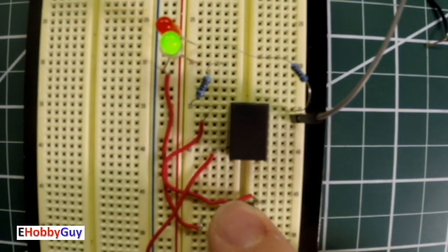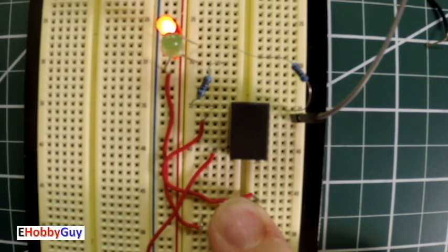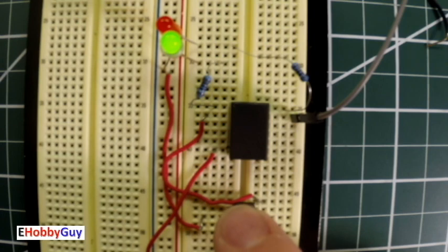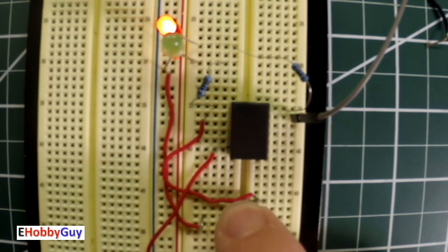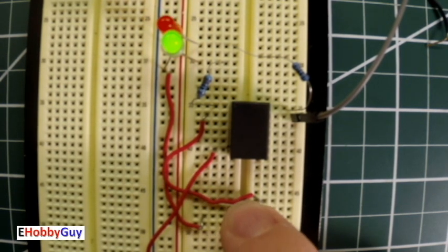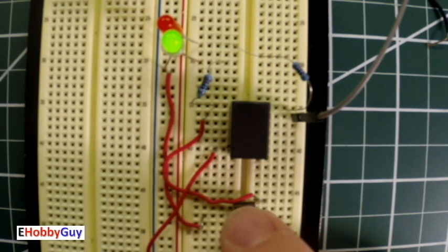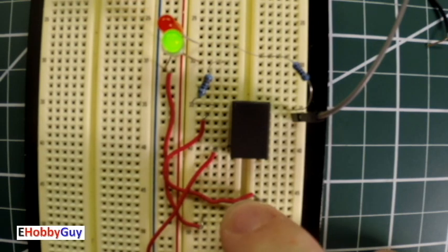When I energize it, the pole switches over to the other throw and provides power to the other LED. While it's passing through space from the normally closed to the normally open, neither of the LEDs are lit, but that's a very short period of time because they're very close to each other. This is just a simple example of a Form C relay wired and being used in a way that switches the power from one source to another when energizing the relay.